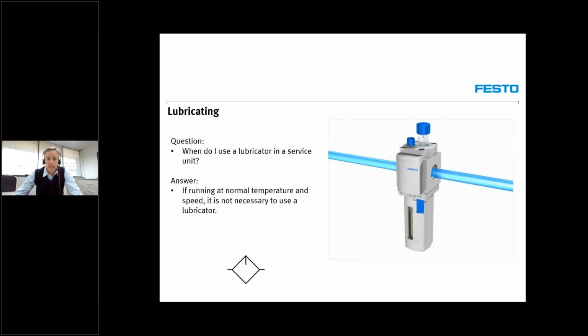However, like I said, if you have lubricated your system before, you need to keep it lubricated and ensure that your lubricators are kept full, because lubrication oil would have washed out any grease in your components.